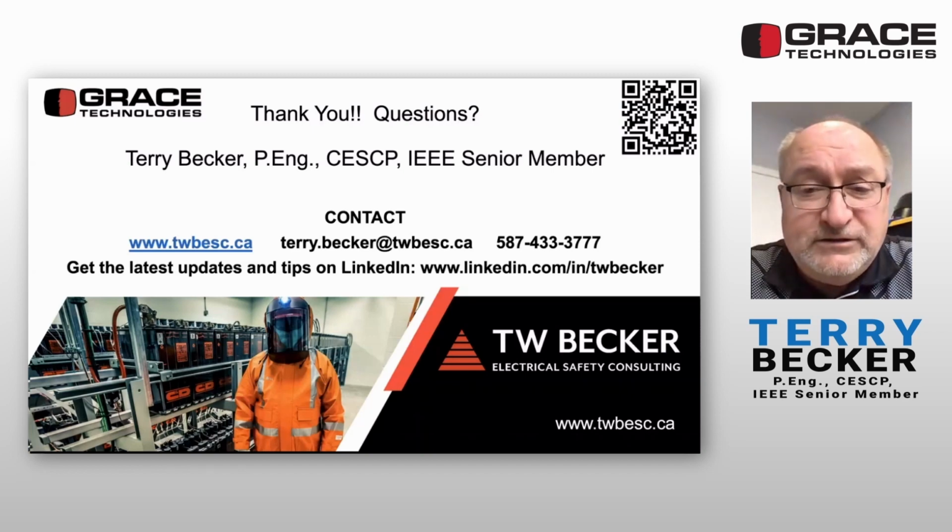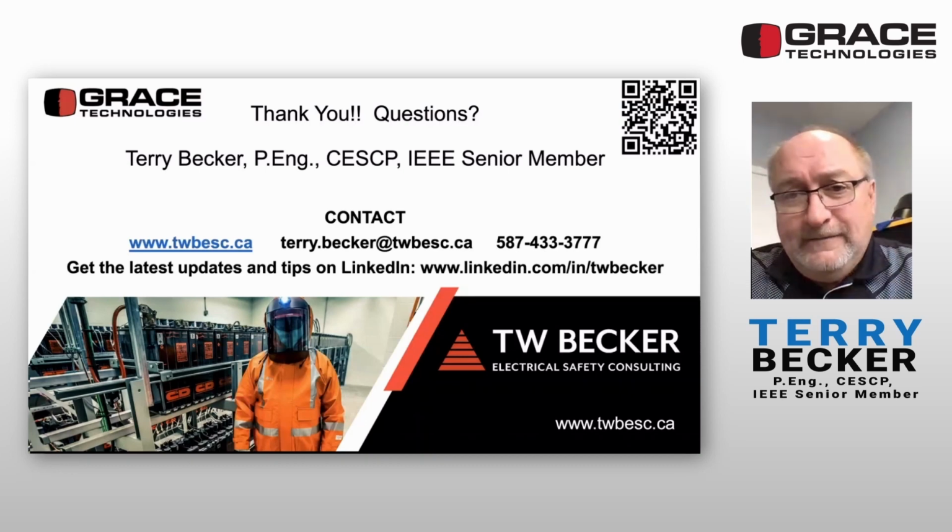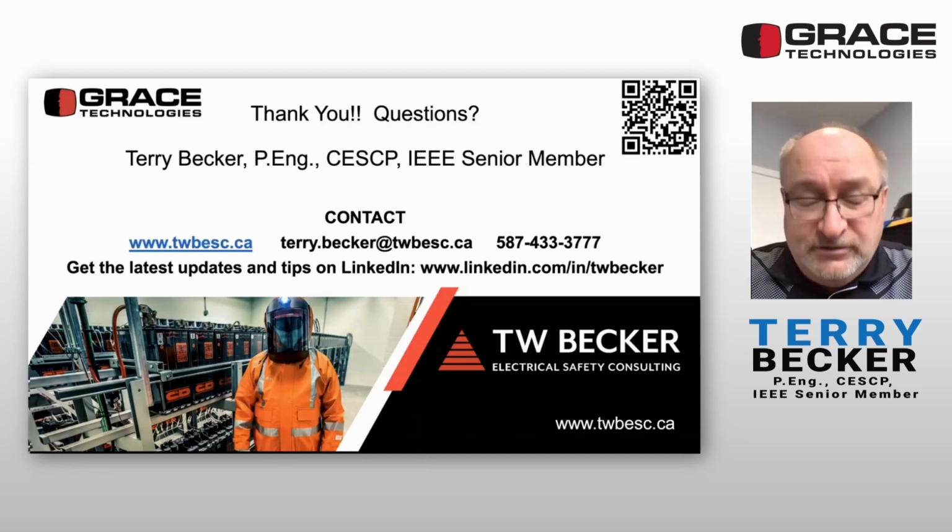Any arc flash event experienced by a qualified person will be a traumatic event. Whether it's 4 calories or 100 calories, it will be, right? But we can protect them from the burn injury up to 140 cals if your company chooses to select and provide that arc flash suit. This will be part of your electrical safety program and your qualitative risk assessment completed.